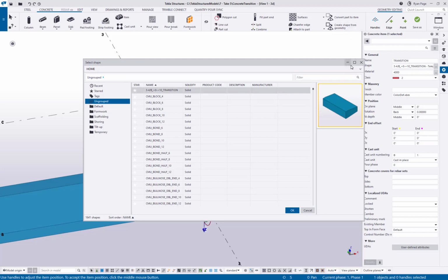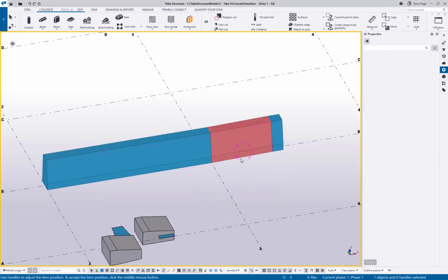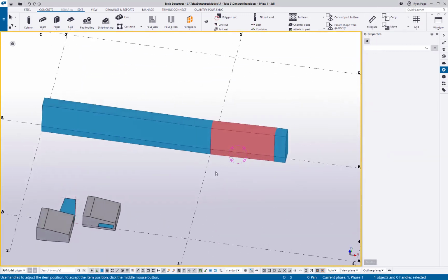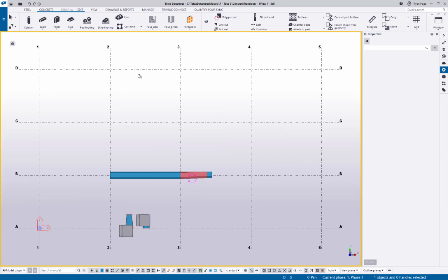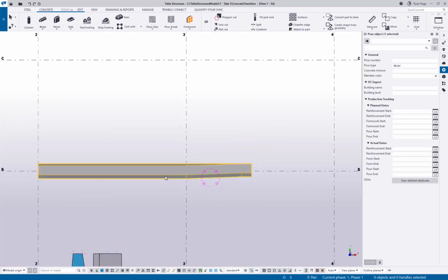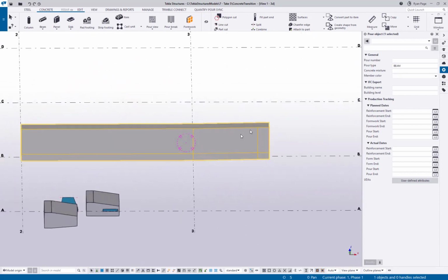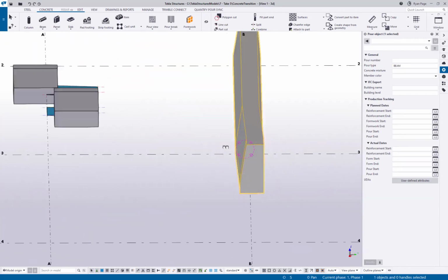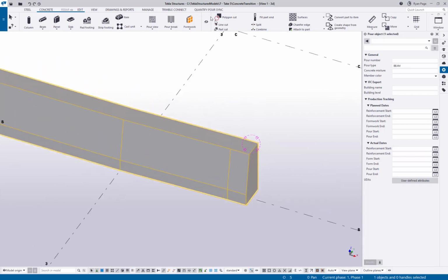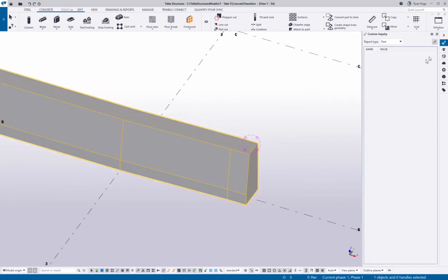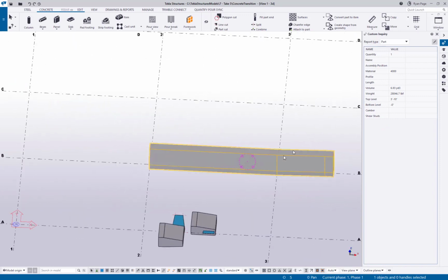The other thing that we'll want to keep in mind is now that we have this piece, well, how do we combine it, right? Well, the easy answer in all reality is turn on pour view and you're done. Okay, allowing our pours to merge when we turn on pour view will give us one contiguous piece of concrete that transitions. This is really helpful, right? We can then go ahead and quickly inquire it to get its volume. This can be part of a larger pour, which will be quantitatively reportable.